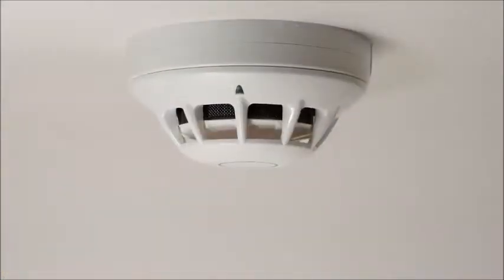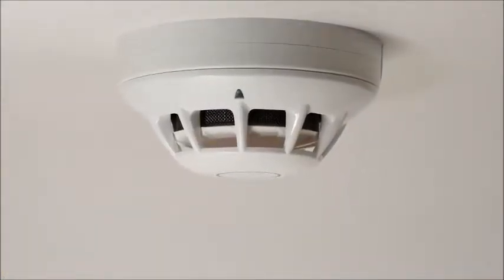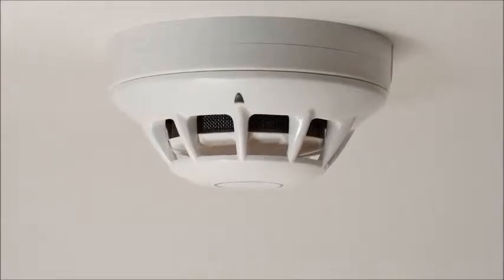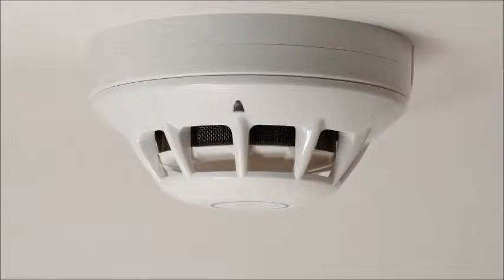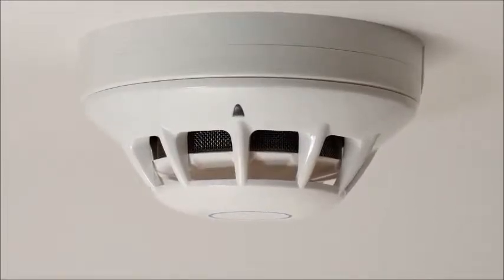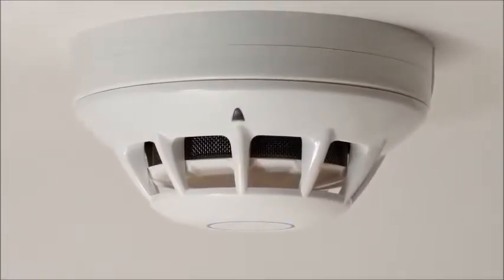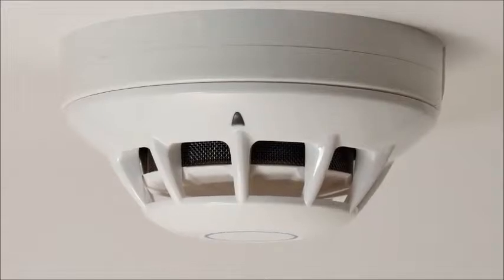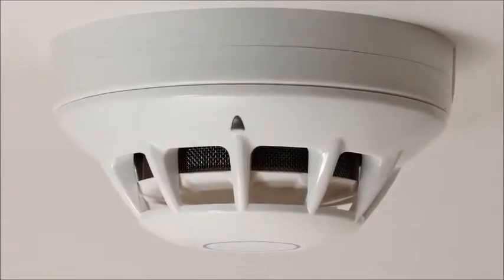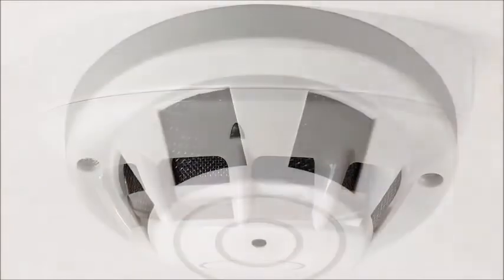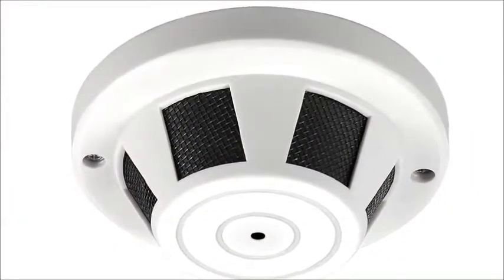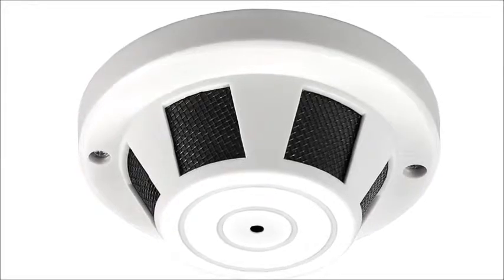Ionization detectors use ionizing radiation from a material known as americium-241. Ionizing radiation is simply radiation from substances that can free electrons from an atom or molecule, the net result being ions that have a specific electric charge of either positive or negative. The detectors use a small amount of americium-241 contained in a small chamber. This chamber is made up of two oppositely charged metal plates that are kept a small distance apart.